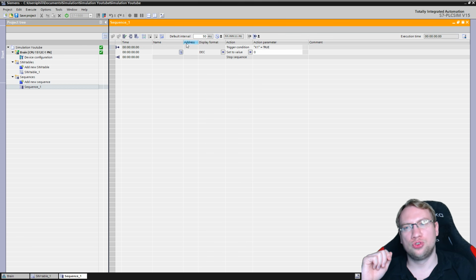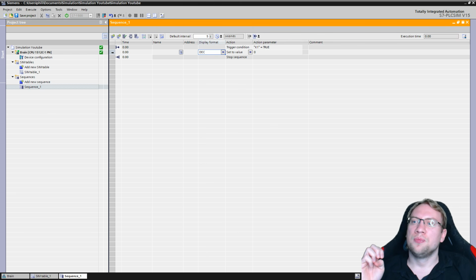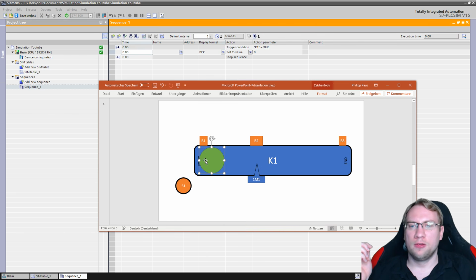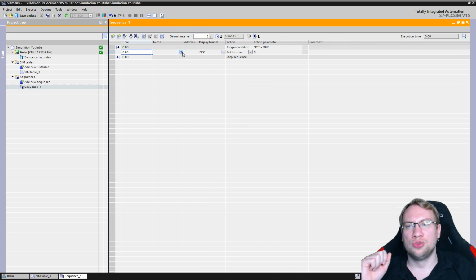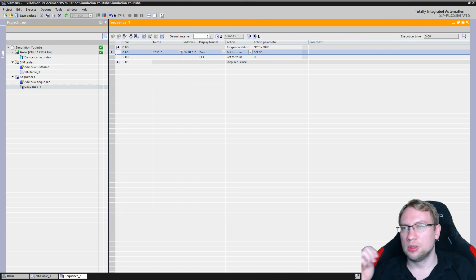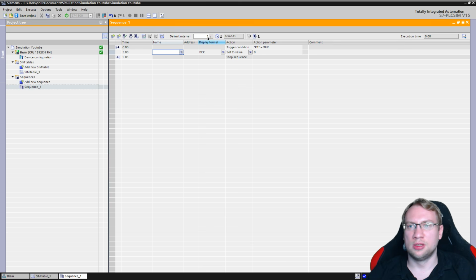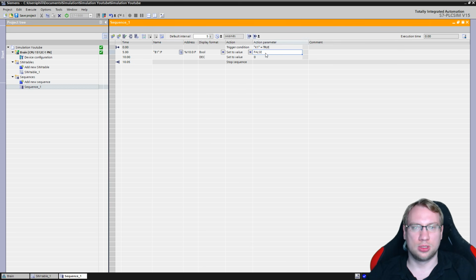As soon as K1 is true, here on top we can just change the time settings. I want it in seconds, and I want one action to be performed every 5 seconds. If K1 is true, what's the first thing that's going to happen? It moves. B1 will deactivate. Oops, sorry, I did the 5 seconds too late. The B1 will turn false, right? That's good. What will happen next?